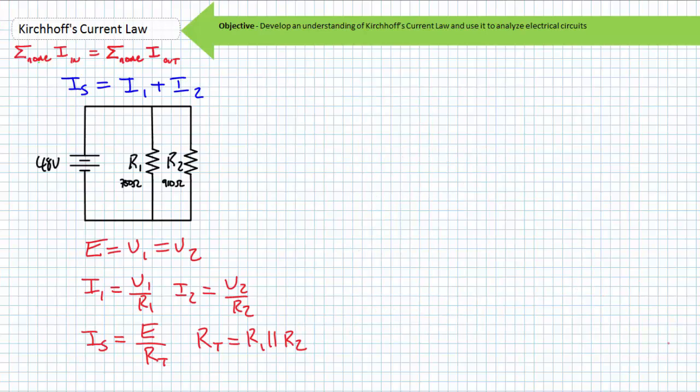Beyond its ability to be used as a substitute or check to Ohm's law, one of the greatest and most powerful applications of KCL is its use in real-world measurement and troubleshooting scenarios, without having to solve for voltage, without having to solve for total resistance or any other make-work stumbling blocks. With a known current input and a single current measurement through either element in a two-element parallel network, you instantly and reliably know the current through the other element using a simple restatement of KCL.